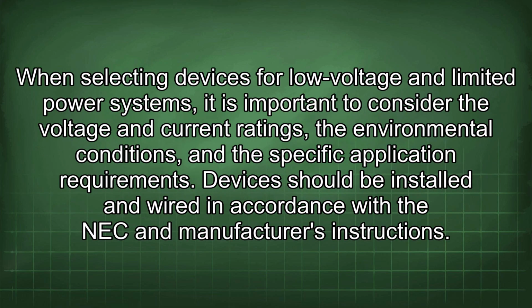When selecting devices for low voltage and limited power systems, it is important to consider the voltage and current ratings, the environmental conditions, and the specific application requirements. Devices should be installed and wired in accordance with the NEC and manufacturer's instructions.